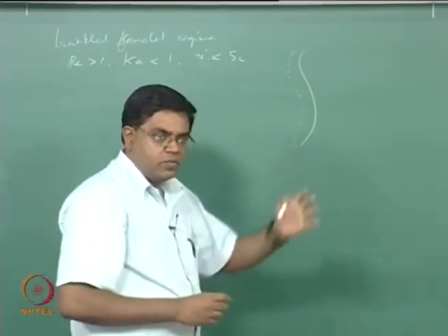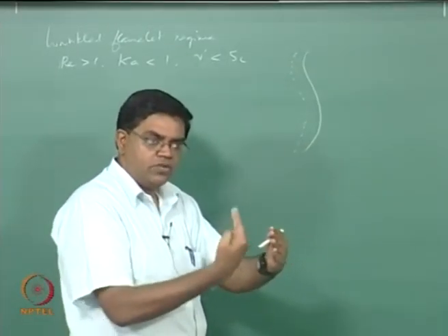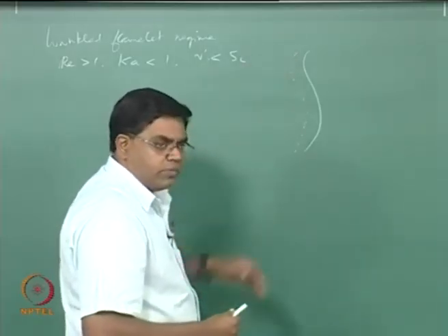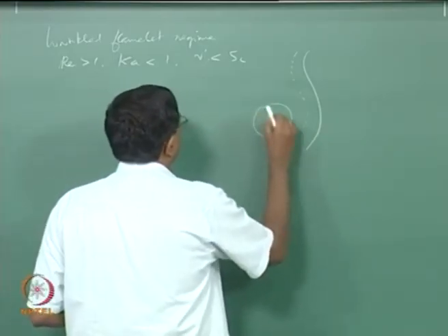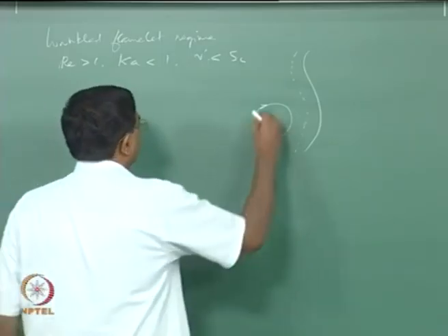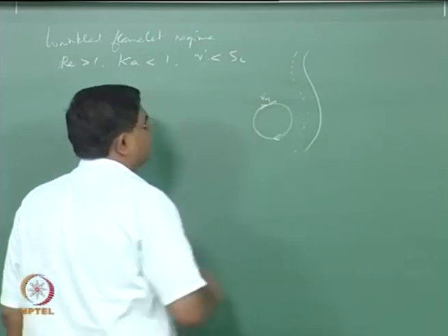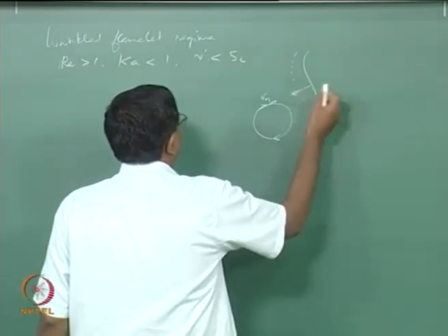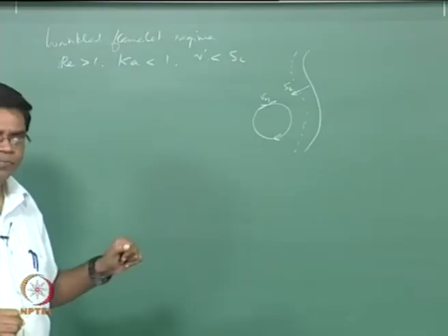Effectively, in a one dimensional flame you would have the reaction zone, and upstream of it the preheat zone. The upstream edge of the preheat zone is what is marked by this broken line, but we are now showing it as curved because it is now interacting with an eddy that is going around like this. Its tangential velocity is Vn, depending upon the eddy size, and this flame is propagating locally normal to itself with a flame speed SL.